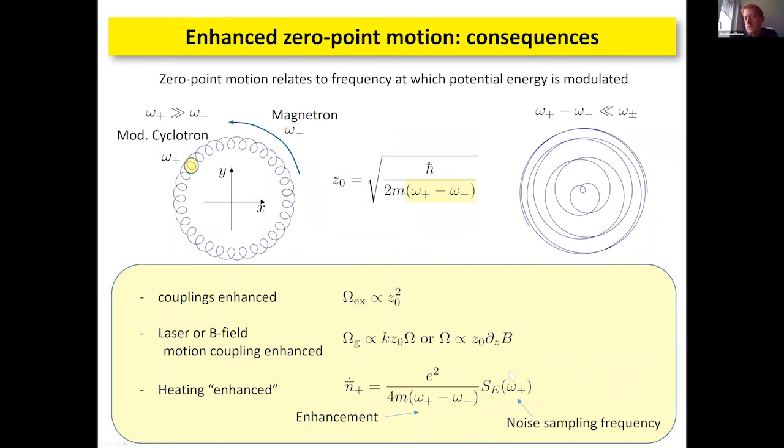Even though you don't sample at the difference frequency of these two, somehow both of these effects appear: you get benefits from going to a difference frequency here, which is far below the actual frequencies of the modes, and you're somewhat protected by the fact that you still sample noise at the frequencies of the modes.